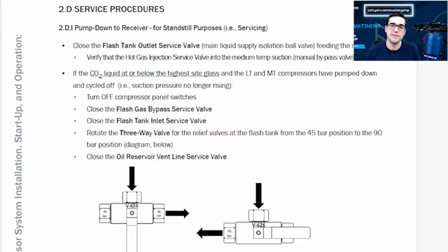And we need to really start troubleshooting while the system's running normally. This is what I'm teaching more and more people to do: when you're out in the field, look at some equipment that's working properly. Instead of just leaving the site and taking 15 or 20 minutes to look at social media, which is not bad when you're on your own time, but when you're on work time, learn a little bit more. Take your meter and go check a few things. Check that relay that's getting 24 volts versus the one that's getting 120 volts. What's the difference? Check if it's 24 AC or DC, because spending time on electrical wire drawings is really important. And then reading the procedures.